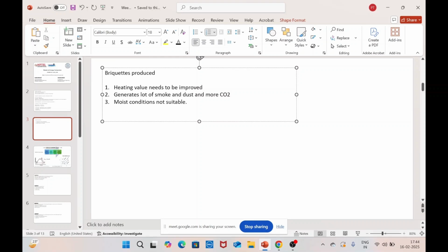What happens is, we have talked about the concept of binder, right? Irrespective of whether it's a low pressure system, intermediate pressure system, or a high pressure system, for the interlocking between the particles you require some sort of binder. Whether that binder is generated inherently or we add it externally is a completely different story. We need to check that the binder should not be soluble in water.